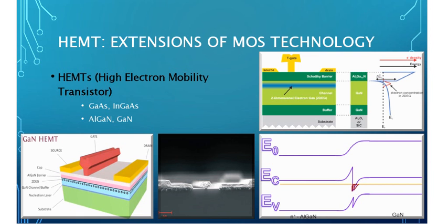Now, these devices seem to solve a lot. They are very fast. However, they still run into problems with the cost of producing them, the production processes. A lot of these involve significant production processes, and in addition to that, there are other things such as not knowing what's going on with the interface traps at these different barriers and fine tuning those. So you can see this will be a major player down the road, in addition to the regular MOSFET roadmap for semiconductors and III-V semiconductors in particular.